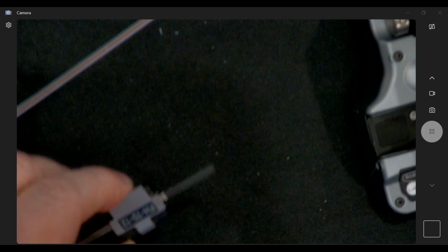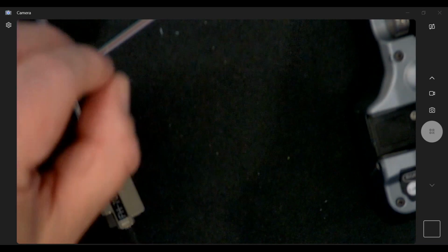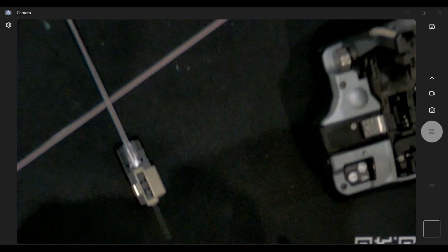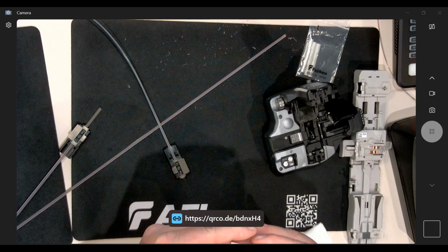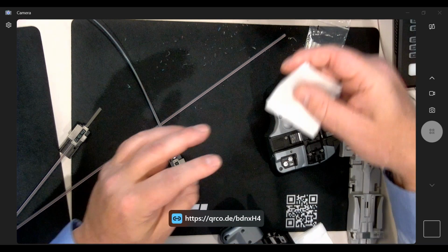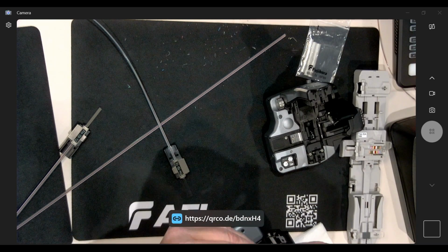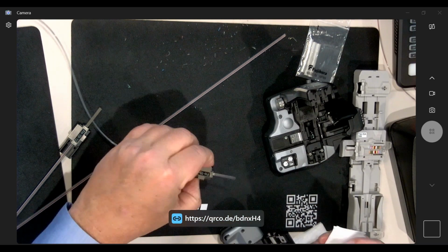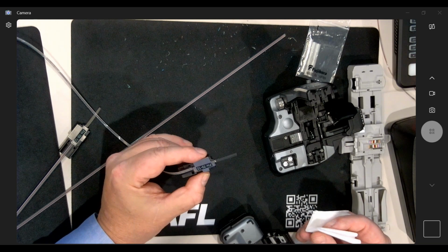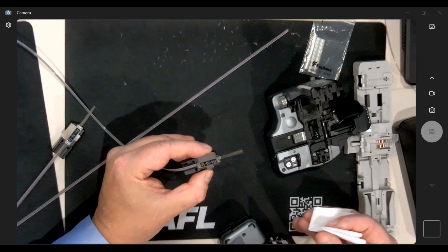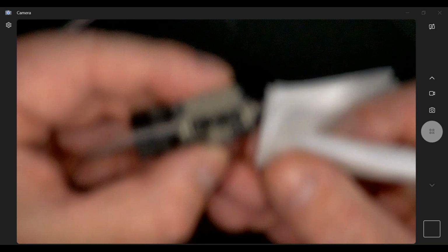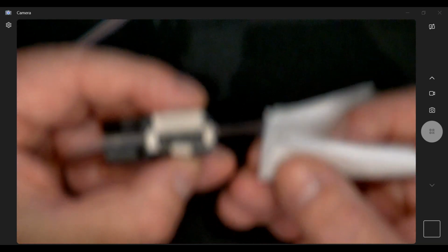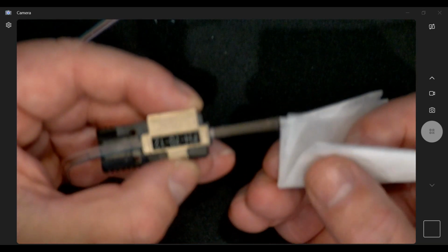Now, I'm going to prep this fiber using a cleaning wipe and an alcohol to clean this ribbon. Now, you can drill down for me, Mega. This is an important step to consider. And again, it's called cleaning the fiber, and I also call this fiber management or training the fiber.